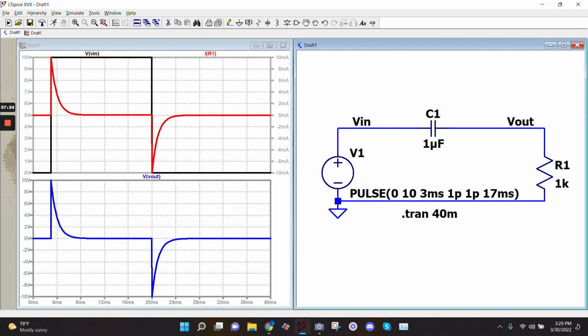Well, this might stay charged, yeah. It'll stay charged. It'll eventually discharge through the other resistances that are inside the brick. But you won't see the light on the laptop, obviously, because nothing's supplying anything, right? I know there's sometimes lights on the power supply, and we unplug it, and the light will stay on. That's because there's still some cap in there that's charged, and it has to dissipate through something. If it's on a circuit board at all, it's connected to something. It can't just be sitting there floating. So it'll eventually discharge through whatever's around it, because everything has resistance.